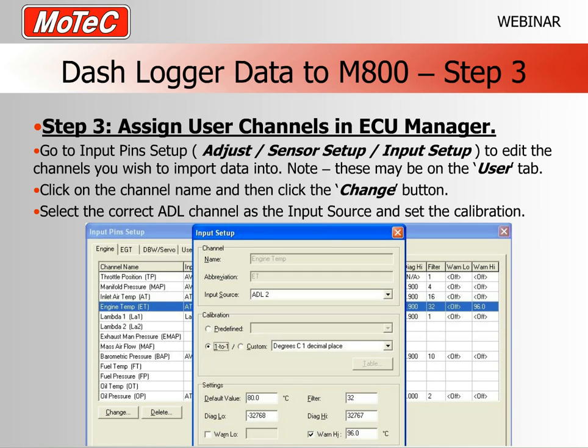Okay, now we have to actually assign each of these channels as an input into the ECU. The only way we can do this is via our input menu, even though these aren't actually input pins. Clearly they're a message rather than an actual physical input pin. So in our ECU Manager program, we click Adjust, Sensor Setup, Input Setup, and that will open up your input pin setup screen,